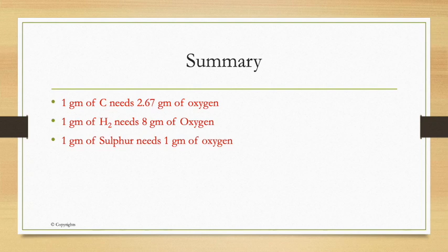What we are going to do is calculate the chemical formula as we have discussed in section 2. After knowing the chemical formula, now you know the number of moles of carbon, hydrogen, oxygen, and sulfur. All you are going to do is calculate the amount of grams of oxygen that you need per the chemical formula. Then you are going to add all the oxygen needed together, and this is the amount of oxygen needed.